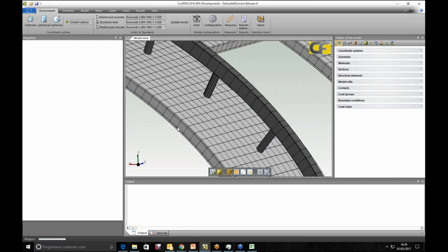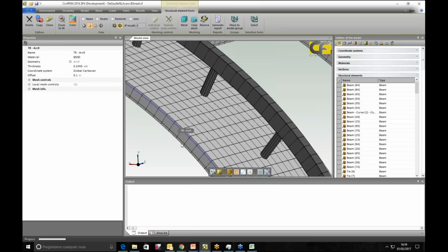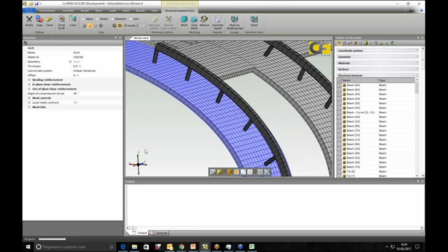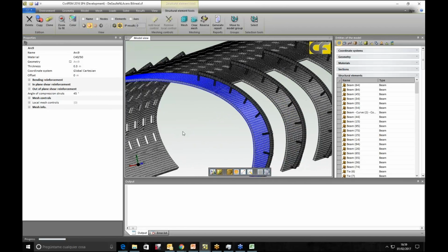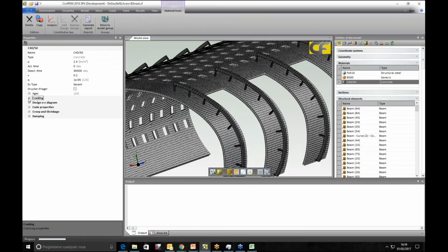That one, and this other one, is where the reinforcement is made. These are cell elements with reinforcement and beams. For these cell elements, in the material we have cracking and crushing behavior. For crushing strains, we add 0.35%. When this deformed shape is reached, the model cracks.